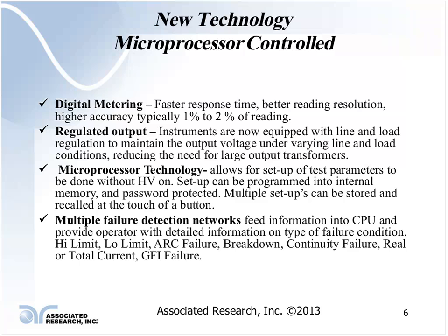One of the things that I've seen in a lot of the specifications is in regards to the calibration of your equipment. Again, a lot of the safety agencies now require that your Hipot tester or your test equipment in general be calibrated by an accredited calibration laboratory. And they may require 17025 or Z540 accreditation, or even a CTL accreditation.